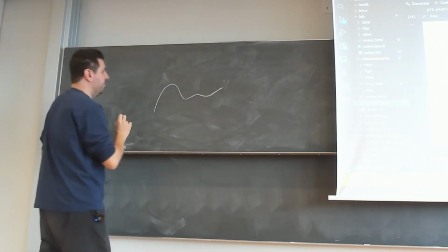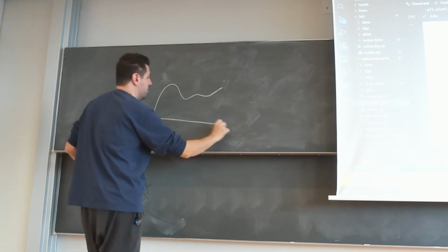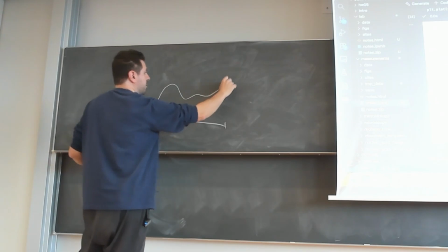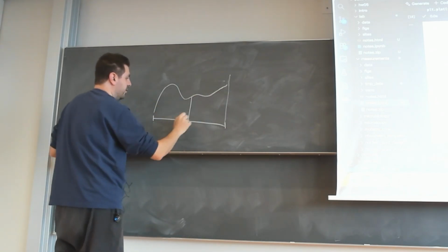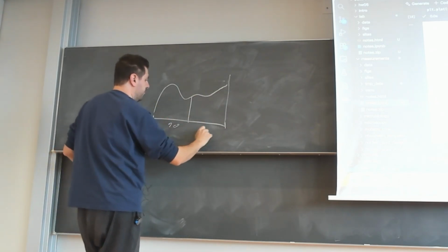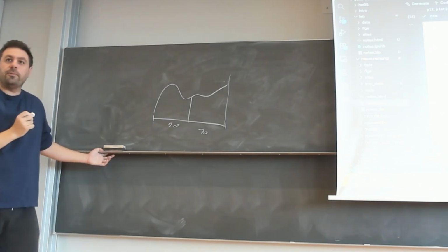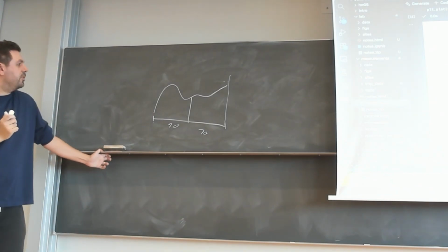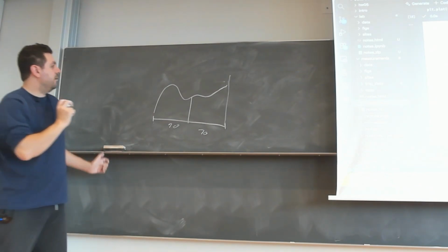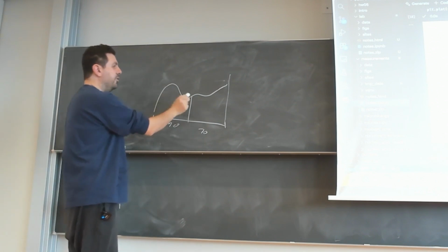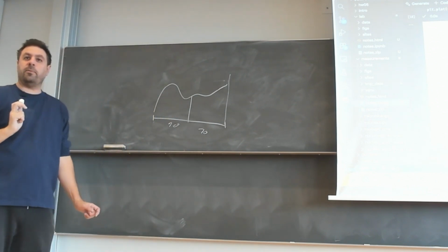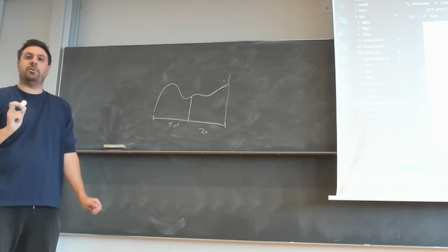So this is our signal, and this is my window. Let's say I'm interested in this. This is 10, 10. When I average, I do something very interesting: I'm fitting a constant polynomial in a least squares way. That's what the average is doing.